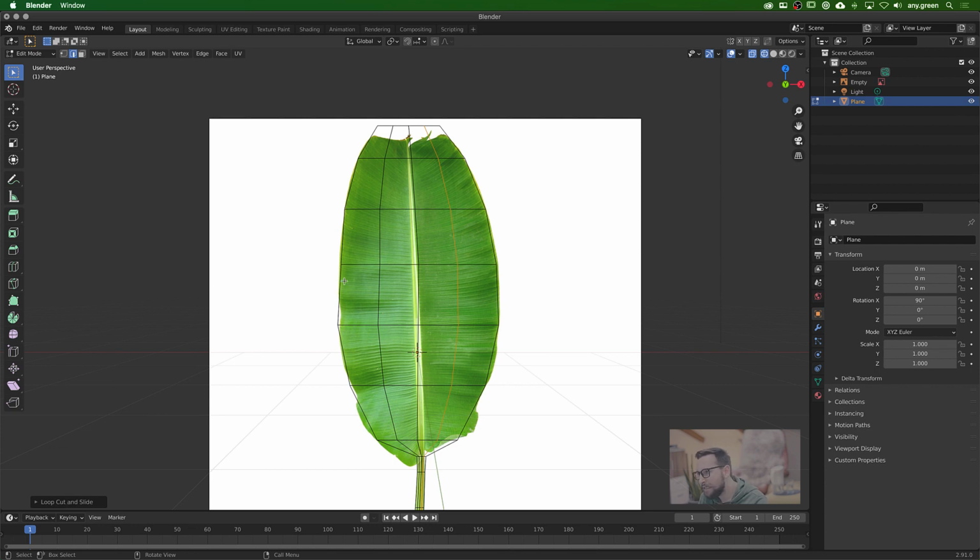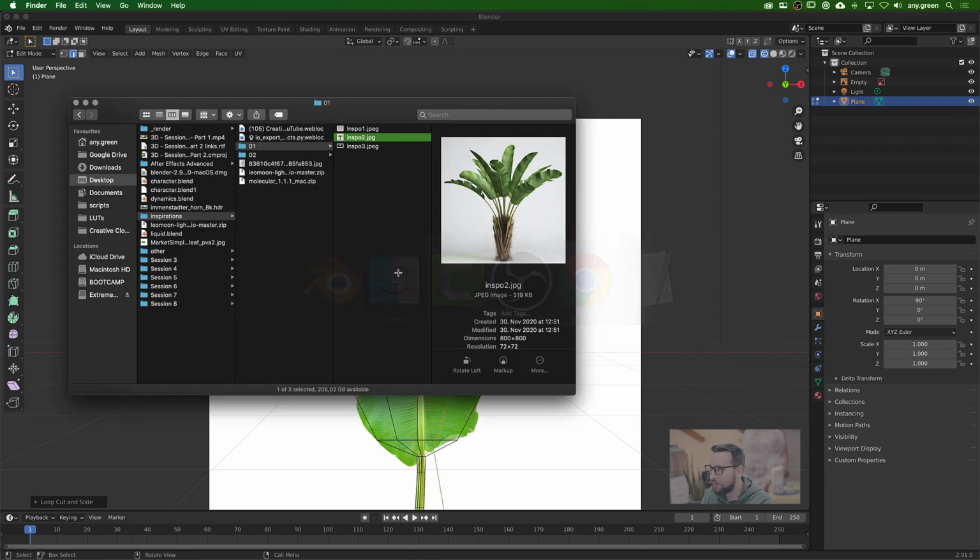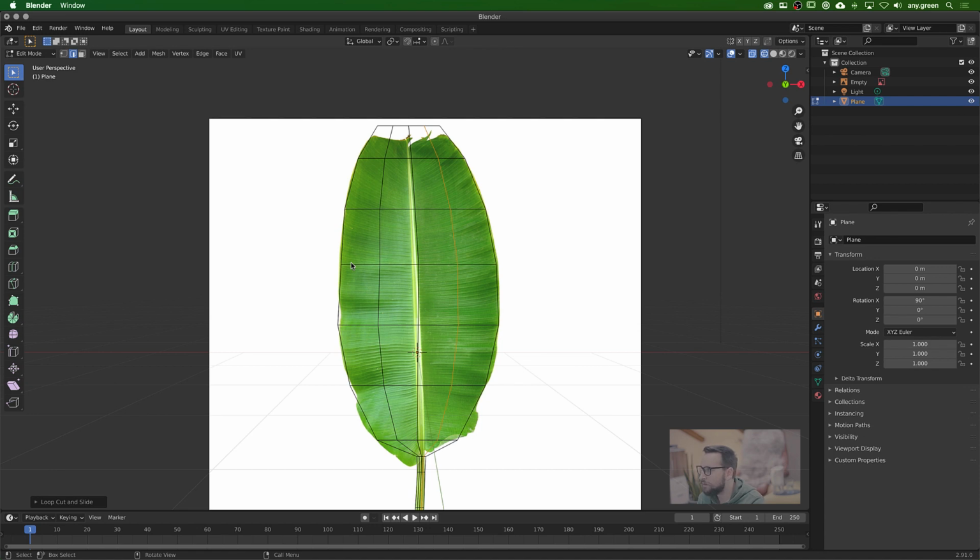All right, now to create kind of like a vein effect here, I will simply create with the knife tool a cut. So I hit K for the knife tool, I click and let it snap to a point here, hit enter to apply. Maybe actually let me do this down here. Okay, and then here, and then maybe another cut up here. Okay, there we go. Oh, wrong shortcut. What am I doing? Click, click, done, enter, we're good.